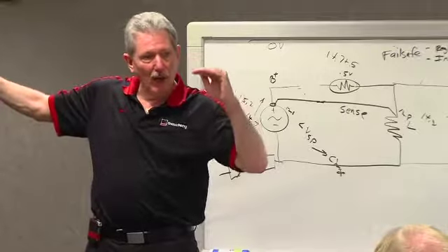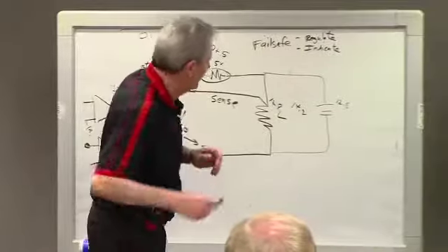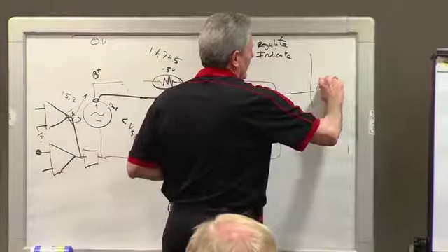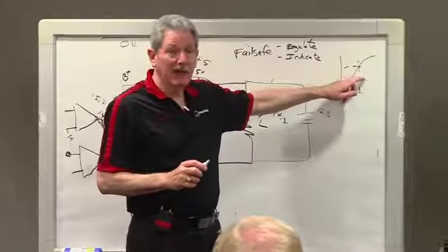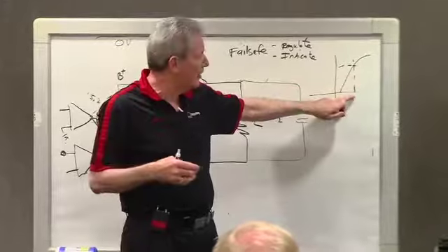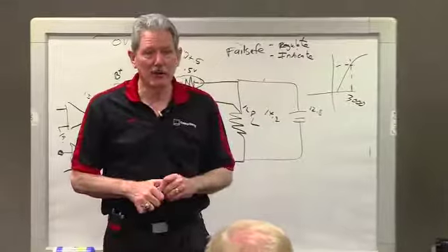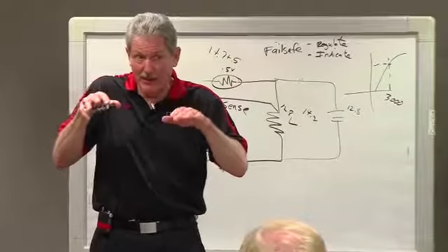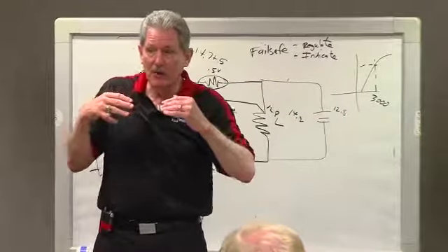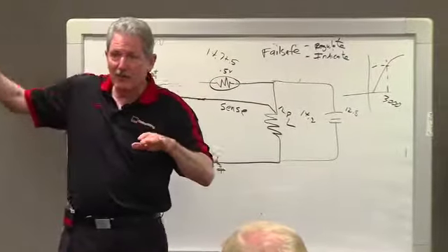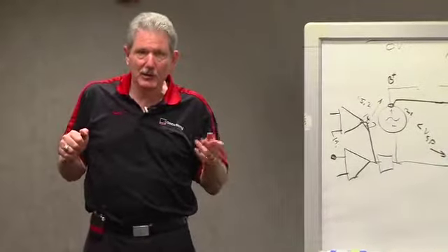So if you're below 11 and a quarter volts and above, going back to the performance curve, up here, you've got more current available than the loads would absorb. So up at say 3,000, you've got plenty of current. So if something is loading the engine or loading the alternator, or the alternator is damaged, now I want to know about it. So I'm below a voltage and above a speed. That's why you have two parameters on undervoltage.